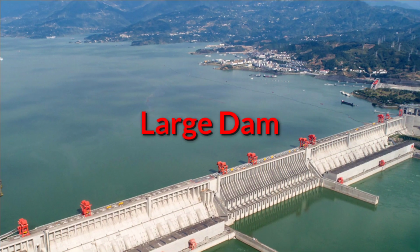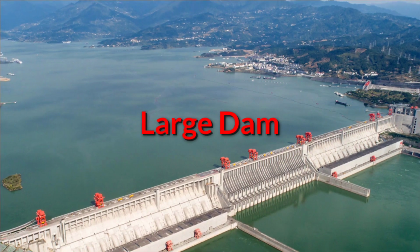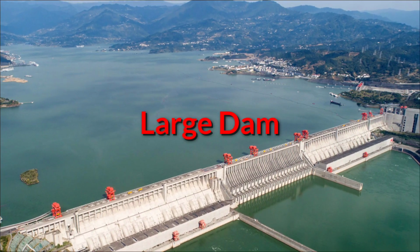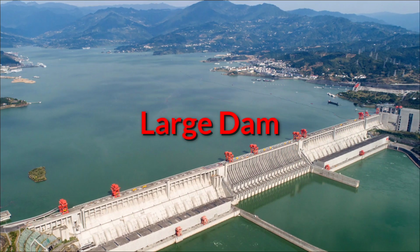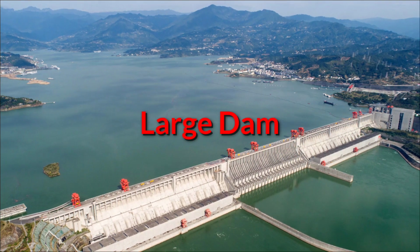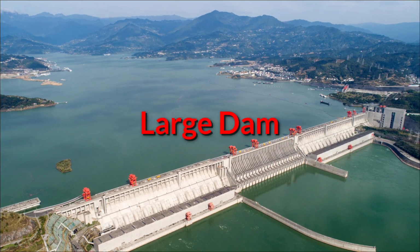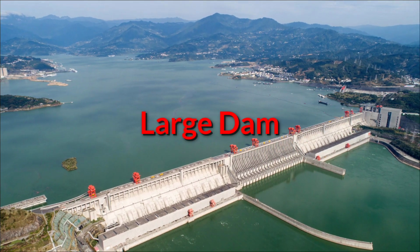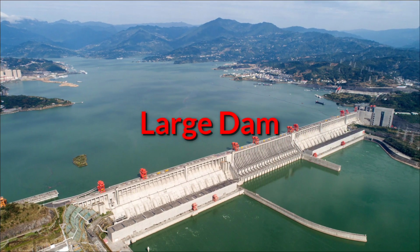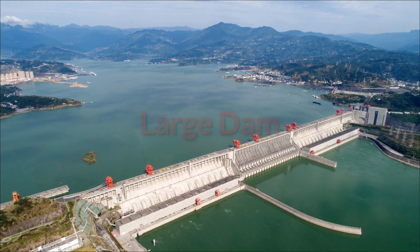For large dams, the International Commission on Large Dams defines a dam with a height of 15 meters or greater from the lowest foundation to the crest, or a dam between 5 meters and 15 meters impounding more than 3 million cubic meters of water, or a major dam over 150 meters in height. Dams between 5 and 15 meters high, or with a reservoir capacity of more than 3 million cubic meters, are categorized as large dams.